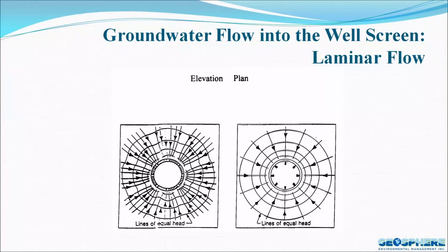If we sit up on our helicopter and we look down into the well screen from above, the one on the left is like our slotted pipe, and we can see how the flow lines with the particles of water are converging and smashing into each other and creating a really turbulent and violent environment, more than we really want it to be. Whereas on the one on the right, we see the lines of equal head. We see each particle coming in there. They're kind of like enjoying each other's company as they flow into the well screen. It just makes life a lot easier and minimizes a lot of the problems going into that well screen.